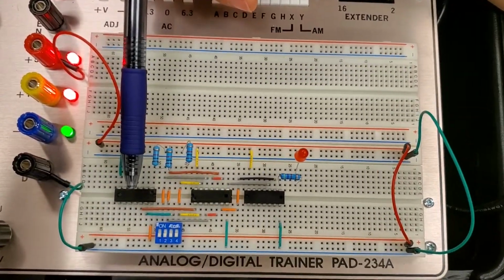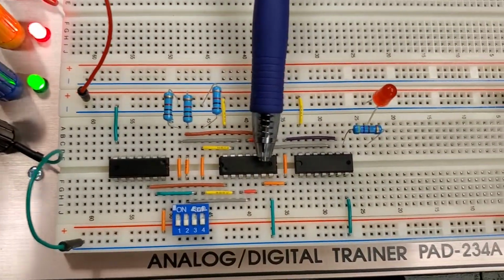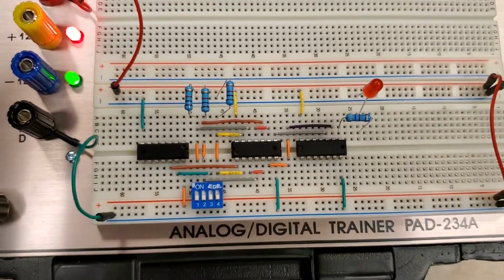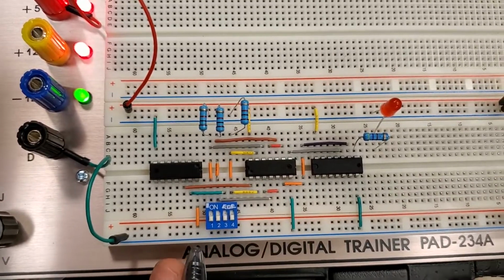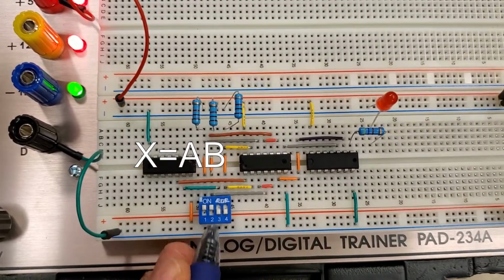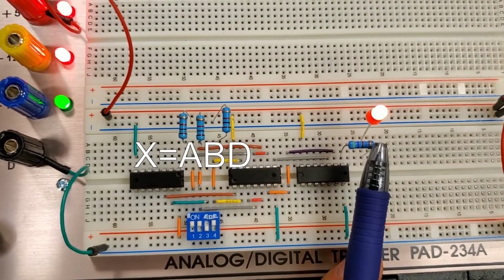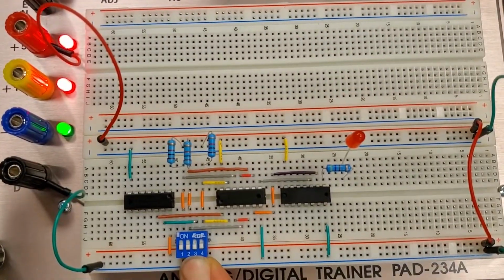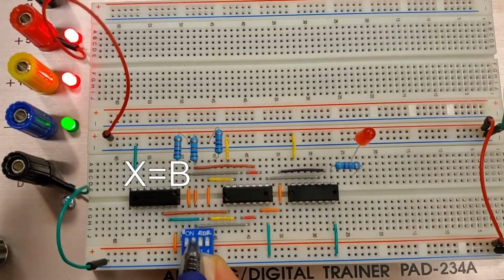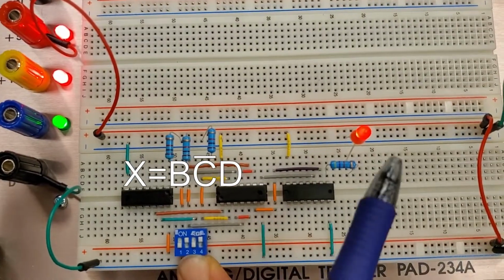We have our inverter chip. This is our AND chip, and this is our OR chip. So you can see if we turn on 1, 2, and 4, our LED will light up. For the bottom half of our logic to be true, we need 2, not 3, and 4. And you can see the LED will light up.